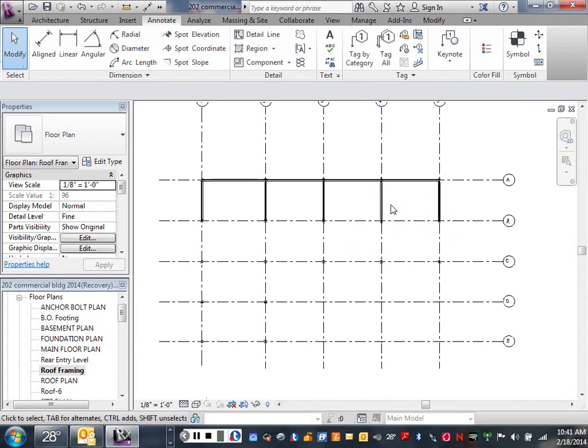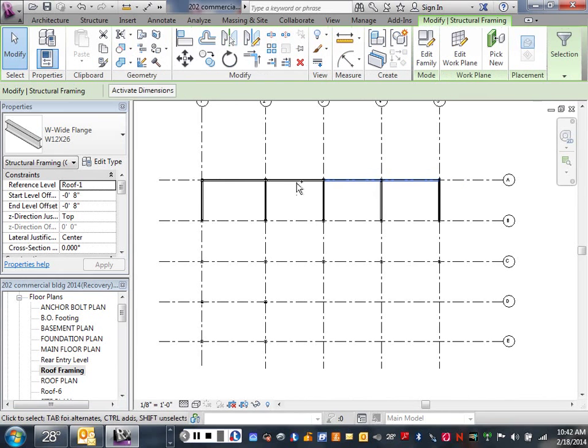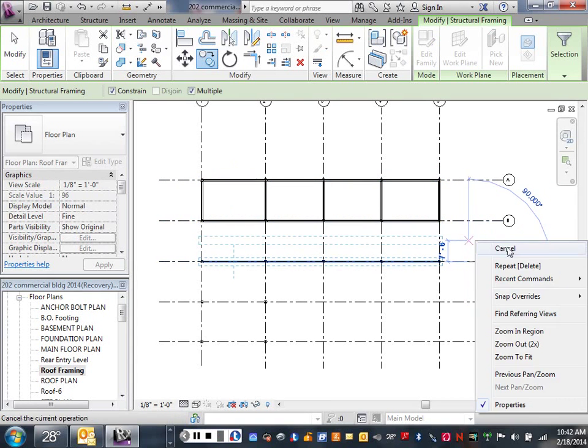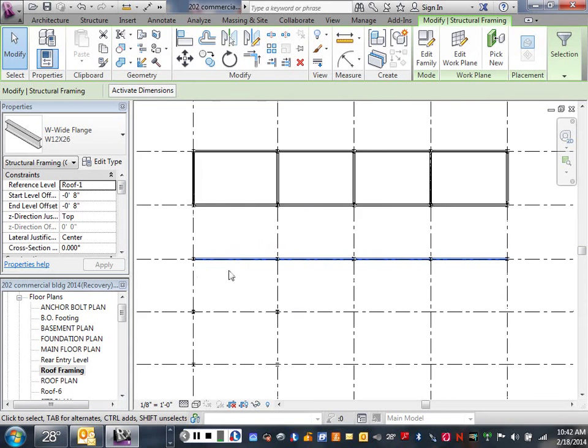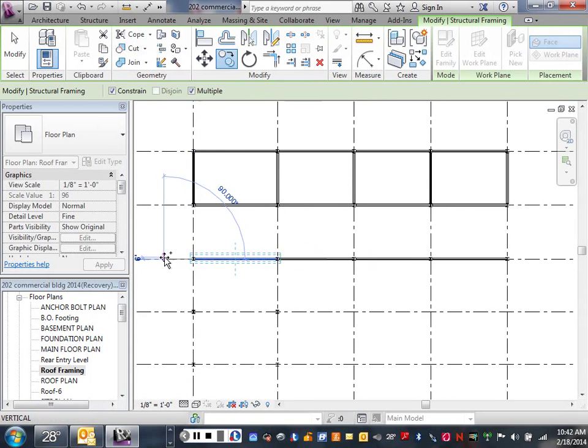And then I mentioned the other day that the economy of structural steel framing is that you have as many beams the same size and same length as possible. So this is another example of drafting time. I can click those beams and copy them from grid line to grid line to grid line, right? Okay, so again, I can have this framework pretty well done here in short order by copying.